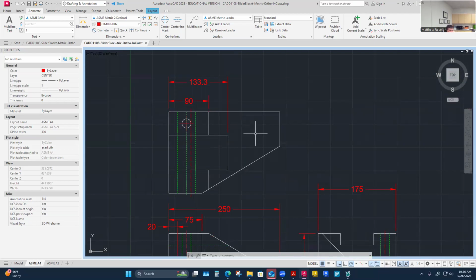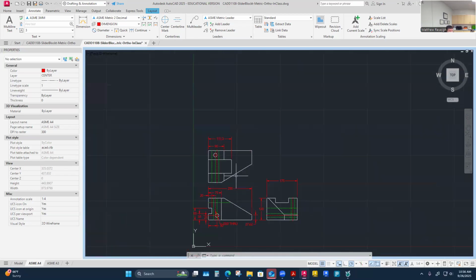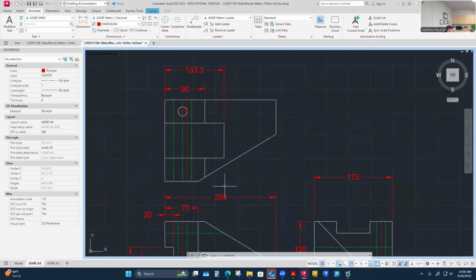I'm not going to really dimension much on this surface because it's also foreshortened in my view. Nothing that I would dimension from here to here is really of any benefit because of that foreshortened slope that's happening that I can't even tell from this view. I just avoid dimensioning foreshortened surfaces. They're just not helpful. I have to dimension them where they exist. So I could put in the degree of miter. I don't think it would be wrong to put in the degrees of miter.